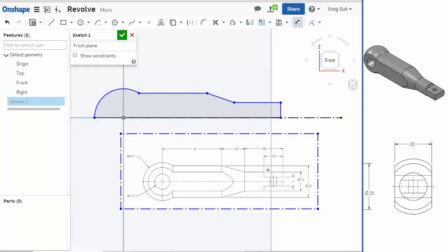The diameter of this one is 15. So if I click on this line, and if I select the center line, this is radius, but if you move your cursor down, that's diameter. That's one of the things that I like about using a center line, because you can directly use the diametral dimension. Okay, this is possible because one of the selections is a center line. If there are like two solid lines, this won't work. Okay, so select the center line, and this will be 15.